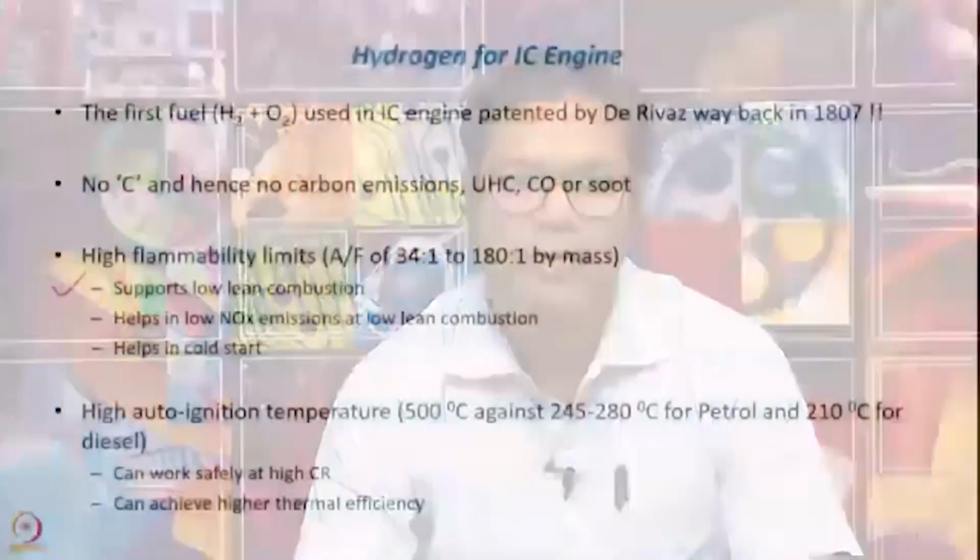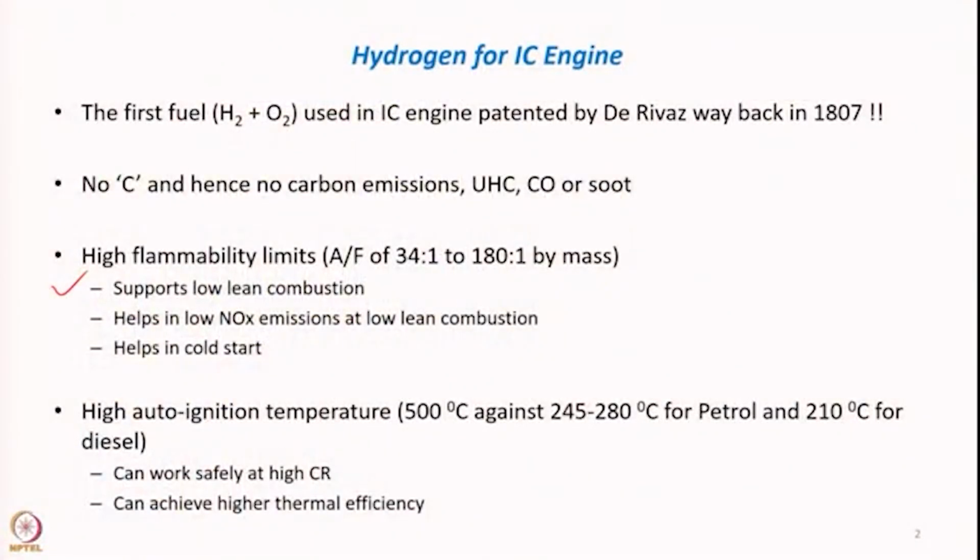Okay. So, now when we talk about the flammability limit, how does it affect or why is it so good? One of the things is it supports lean combustion. We will shortly discuss this lean combustion, which helps in limiting the NOx emission at low lean combustion. It also helps in the cold start.